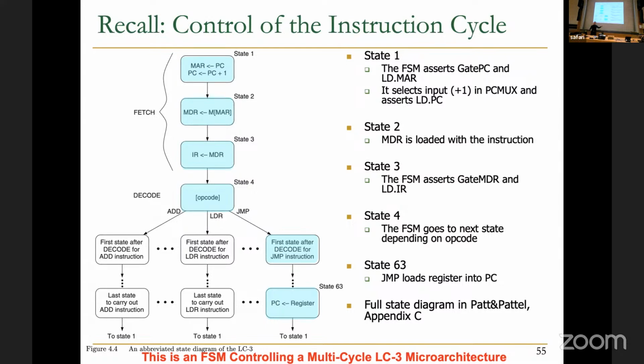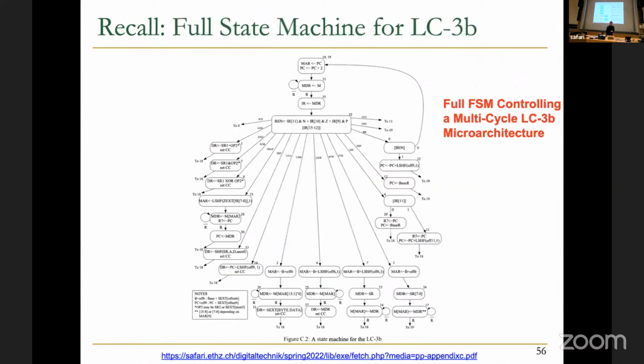And this says nothing about your clock cycle time. Your clock cycle time is determined by how long it takes to finish the worst possible combinational logic delay, as dictated by your finite state machine as well as your data path design. So it really depends on how you design and implement this finite state machine in real hardware and in the data path. It's not dictated by your worst-case instruction, if you will. You remember the full state machine. We'll probably get back to this particular finite state machine, depending on how fast we progress today. We can do a lot of cool things with this.